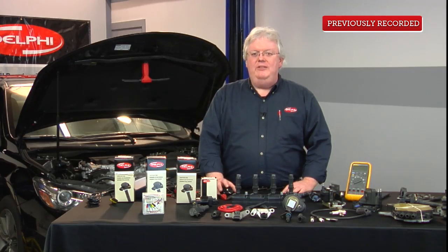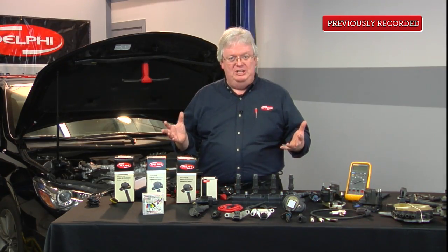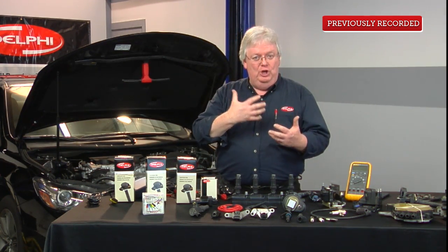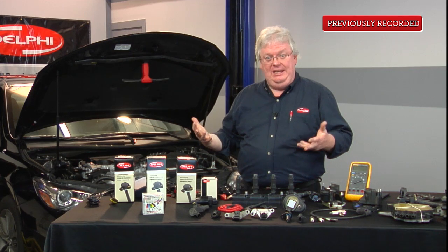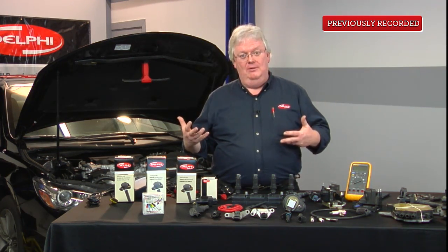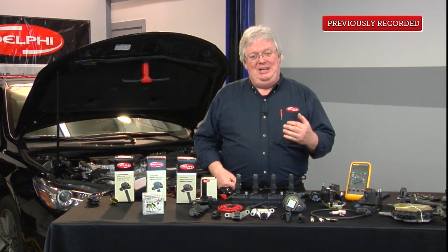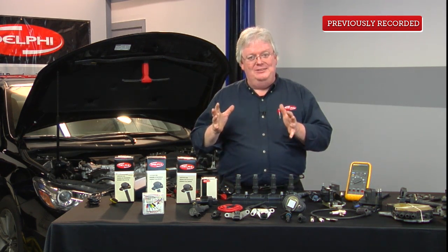All right, we've got a question here, and he would like to know, you mentioned 20 amps at the coil. This is the initial amperage and not sustained, correct? Correct. In fact, if you had a fast enough scope, you could see some inrush, the sudden surge of a 0.6 ohm load applied to, let's say, a 14.5 volt supply from the battery being charged with the alternator charging. But it's not going to be sustained. It's just for a few milliseconds of on time.